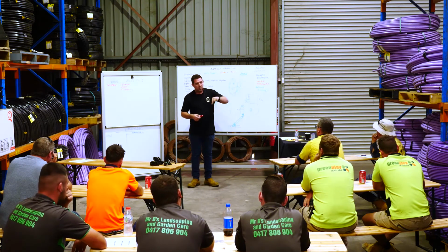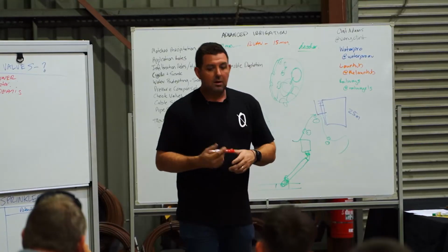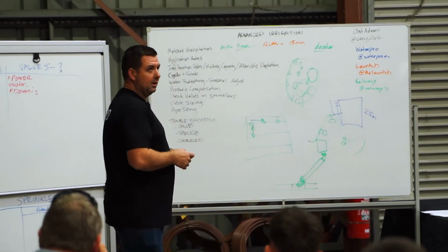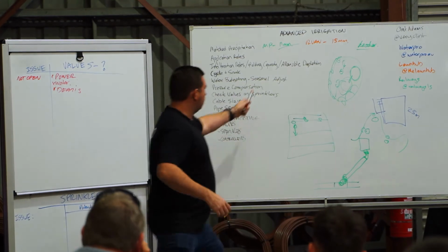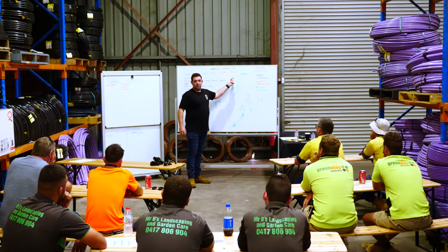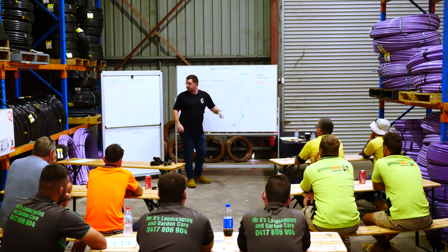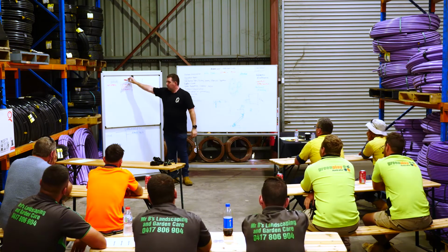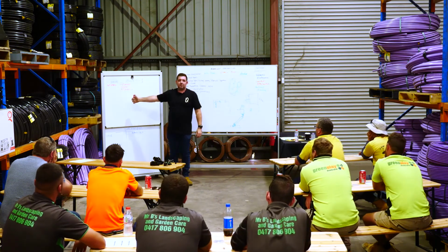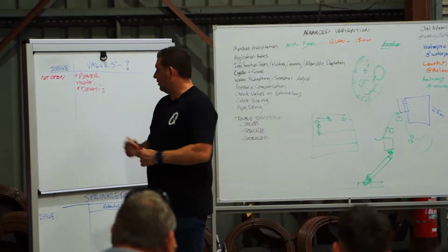They've got a feature where you can hold them up and it flushes water through the nozzle. They're the ones I was talking about before. That could be a thing worth looking at. The unfortunate thing is, if you've designed a system at 11 mil and you want to retrofit nozzles at 15 mil and you don't have the flow, it's not going to work. So not opening is probably 30% of the time. Not closing is the main issue.